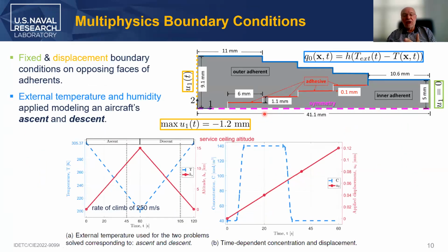So what are the boundary conditions for this problem? We really try to find some boundary conditions that locally represent what the joint is going to see as a result of the flight conditions. So in this case, we fixed the right end and we applied a load here on the left side that is either horizontal or vertical or combined because of the bending that the skin layer sees on the top and the bottom of the wing.